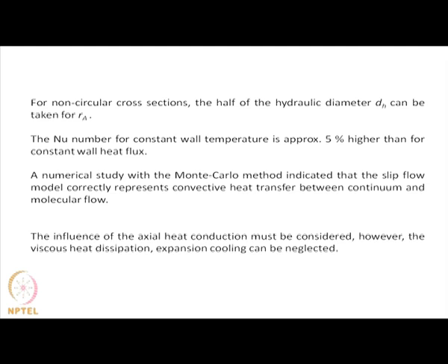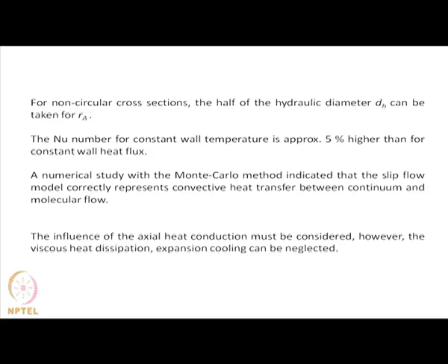since we have more mobility of the molecules in rarefied condition, the Nusselt number for constant wall temperature is 5% higher than for constant heat flux. A numerical study with the Monte Carlo method indicated that the slip flow model correctly represents convective heat transfer between the continuum and the molecular flow, and the influence of axial heat conduction must be considered, but the viscous heat dissipation, evaporative cooling and expansion cooling can be neglected for flows in microchannels.